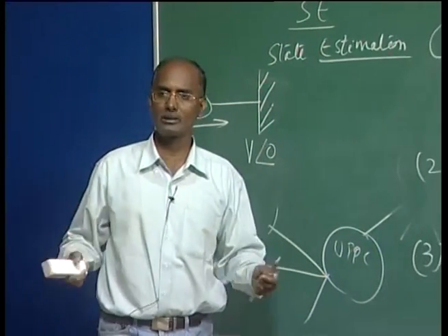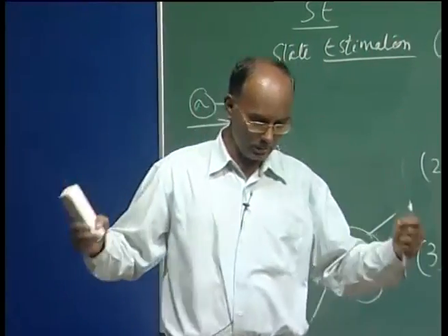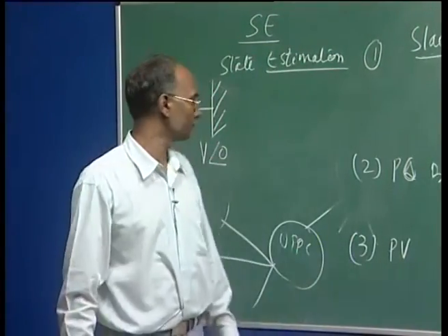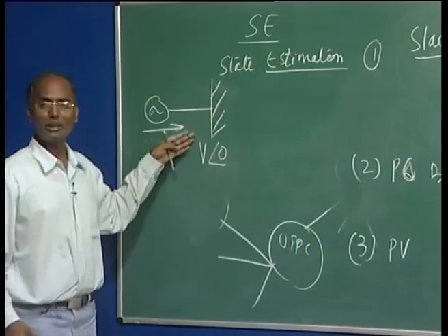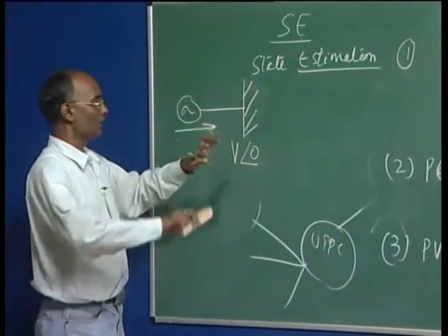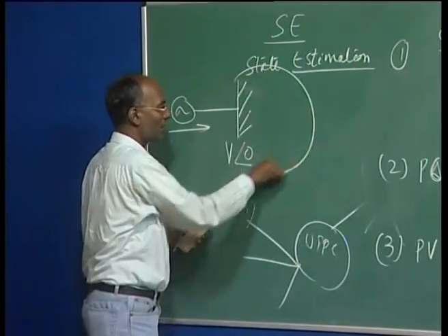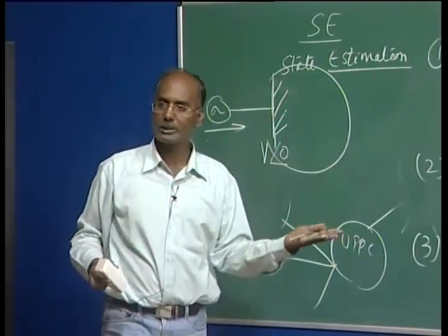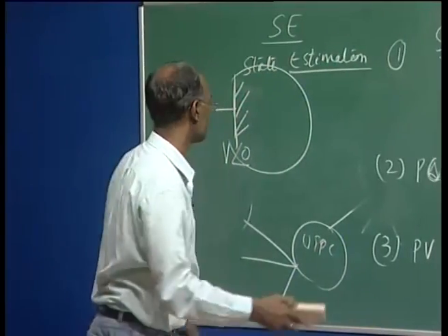Although there is no infinite bus practically, a very strong grid or big bus can be treated as an infinite bus. This analysis is normally used in stability analysis, because we can make your whole system equivalent to an infinite bus, and this generator's behavior we can analyze. So especially this is used in the stability analysis.